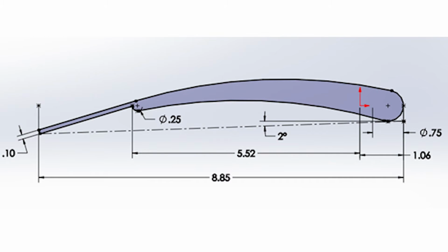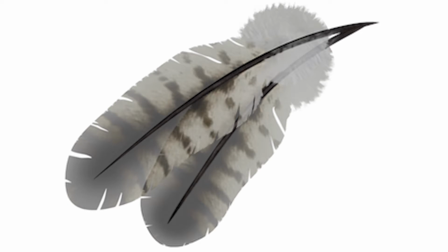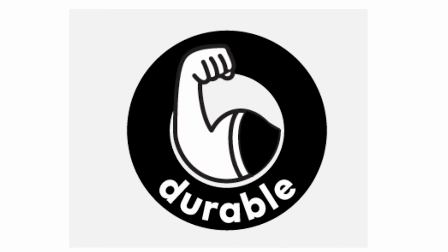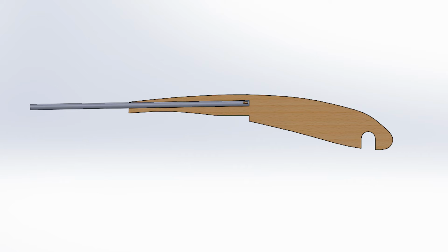After we had the appropriate dimensions, we were faced with the challenge of determining materials. Since our ornithopter isn't an actual bird and we don't have access to feathers, we needed to choose materials that were durable enough to survive a crash, yet light enough to allow for flight. This is a CAD model of our final design for the airfoils. The thick bone and muscle portion of the wing is made up of balsa wood, while the thin feather portion is made up of flexible carbon fiber rods.